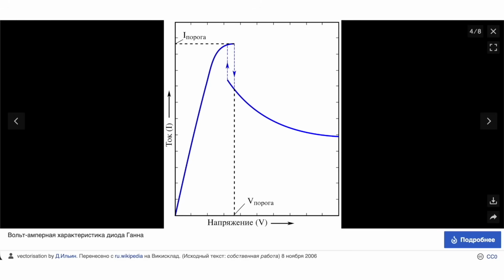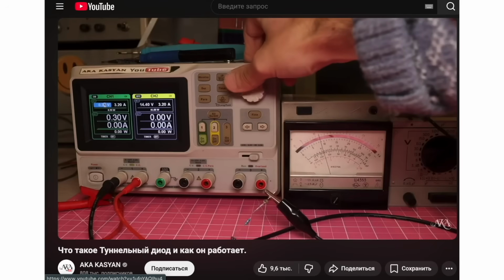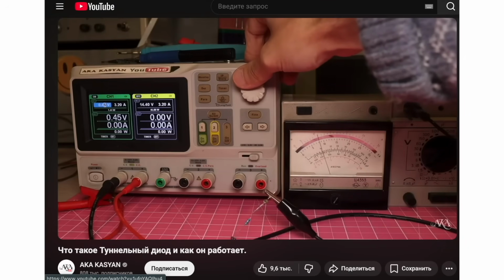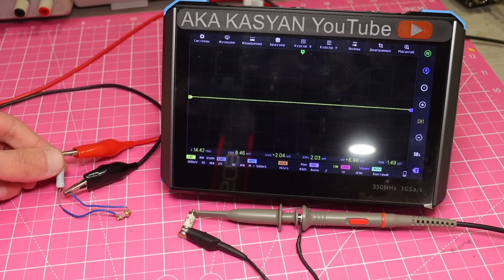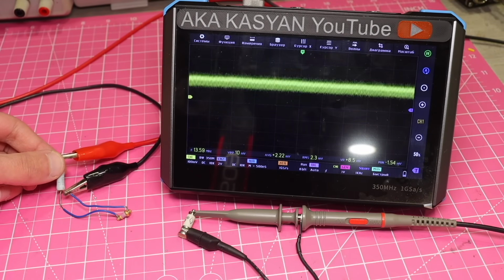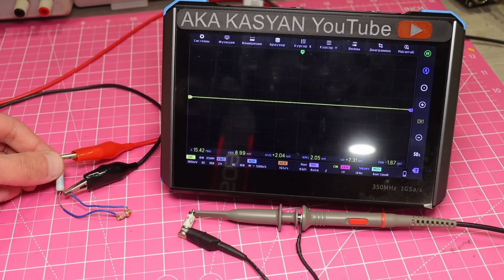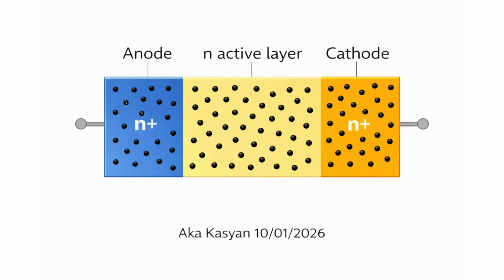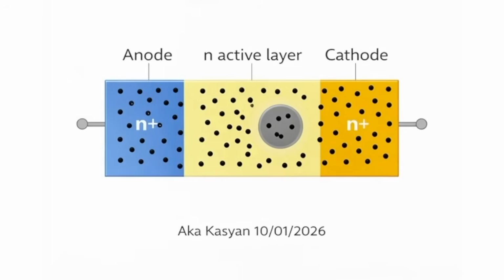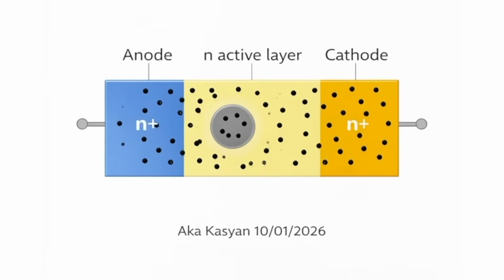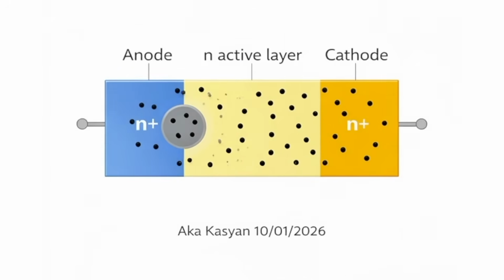Third, negative differential resistance. At this moment, a paradox occurs. We increase the voltage, but the current drops because some of the fast electrons move into the slow and heavy side valley, causing instability in the crystal. A cluster of slow electrons forms, which moves toward the anode, disappears there, and then a new domain is born. These cycles create microwave oscillations.